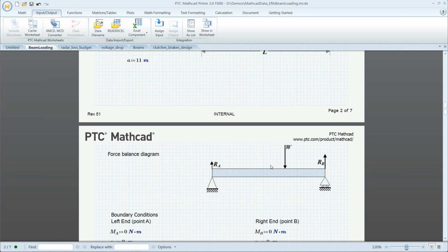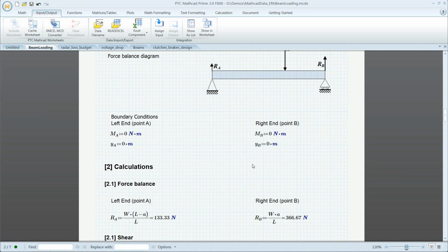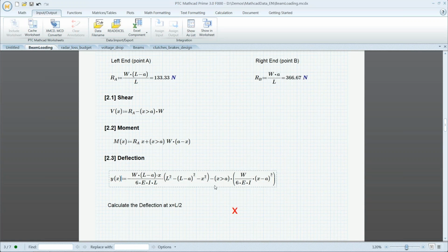Okay. So we're going to go ahead down and actually do some calculations with those variables that we made up above. We're going to find our deflection. We just set those unit variables a couple seconds ago, so we're going to reuse them here and calculate out this big formula for deflection down here below. And we see again that Mathcad's default is meters, but to change that, just retype whatever acronym for the units you want, and it'll update for you.